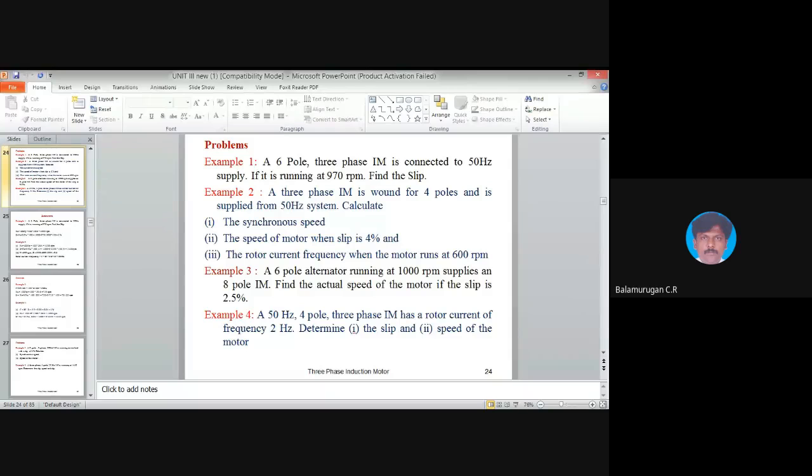150 RPM. Okay. So next you will come here and you find the value for N. So you know the NS value is 150, slip is 2.5%. And from this you calculate the N value. So you tell the exact N value. So N on the 731.25 correct.